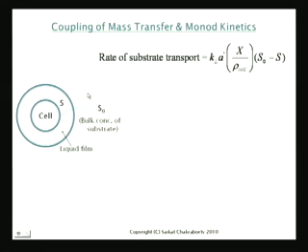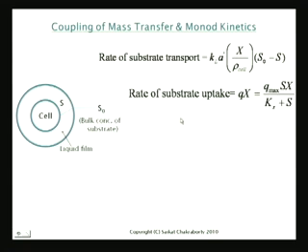The uptake is due to the reaction in the cell, right? So what would the uptake be? We already did that, the growth. We did the growth model. So if we are using a Monod model, for example, what would be the uptake? The uptake is what I gave here, which is S times X divided by Ks plus S times q max. So q times X is exactly the Monod growth model, if you remember.